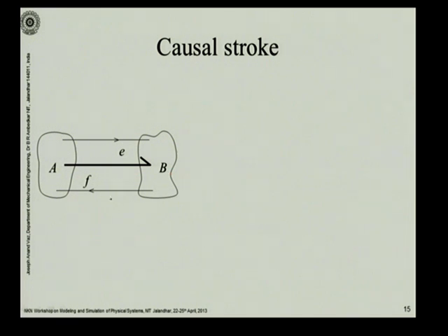We are not going to use these single arrows in our bond graph. So how do we model this? How do we represent it? This is the flow receiving end and this is the effort receiving end. What we do is we place a simple stroke. You see this?